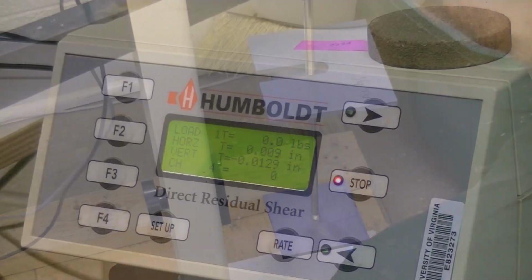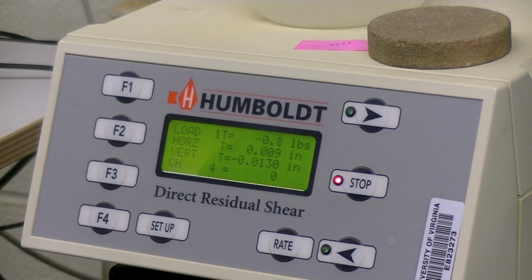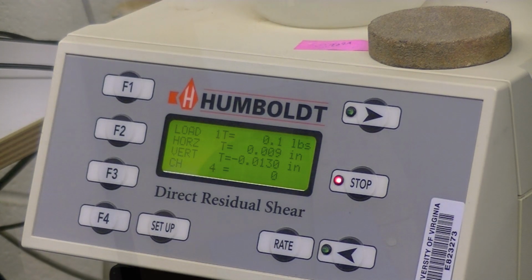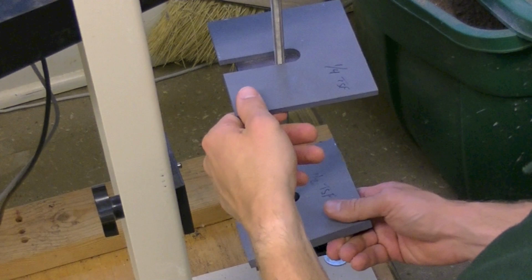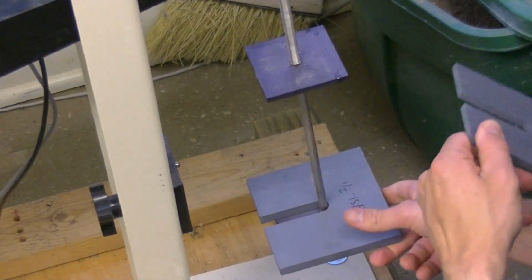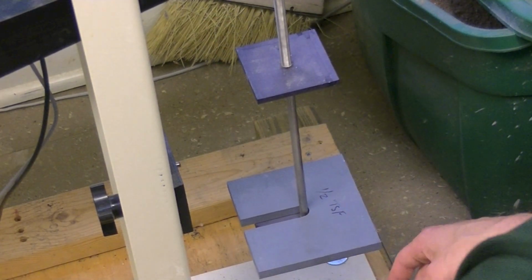For the stresses above the pre-consolidation pressure, normally 1 TSF, plot dial reading as a function of log time. Also plot dial reading as a function of square root of time. These plots are helpful in determining important consolidation parameters.